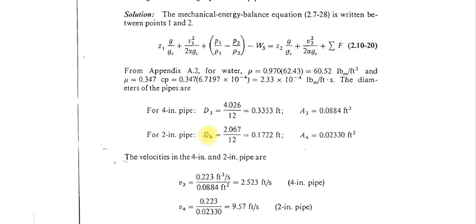In the exam generally these values are given to you, or the table of schedule numbers is given. In the schedule number tables, you have a column of the nominal diameter, then a column of the schedule number, and based on that you can determine the internal diameter. I will explain in the next class how to use the schedule number charts.